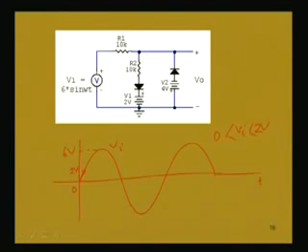So, the current will be flowing in this direction, this point is positive, this point is negative. With respect to this ground point, what will be the voltage that is asked? This is 2 again plus I into R2. So, the whole voltage across these 2 points is 2 volt plus I into R2. Now, what is I? That has to be found out.